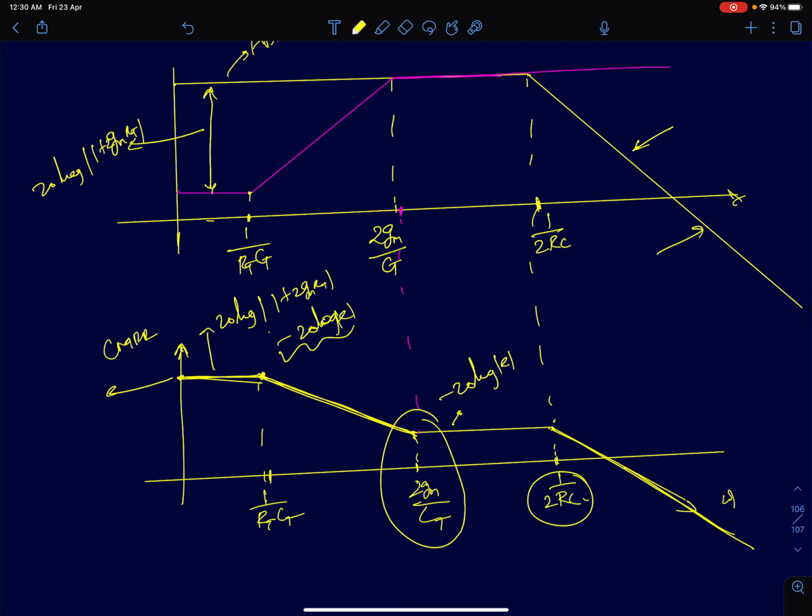That's what this analysis is telling us: CMRR degrades significantly at high frequencies because common mode gain remains the same, but differential mode gain is decreasing. Because CMRR is getting poorer and poorer, at very high frequencies common mode signals will start dominating in your amplifier output in the presence of mismatches, and it will dwarf the differential signals itself.